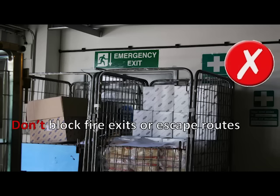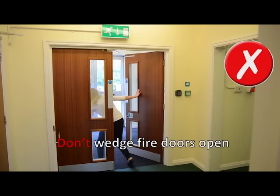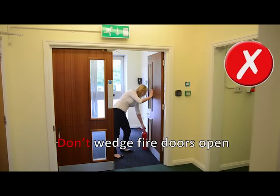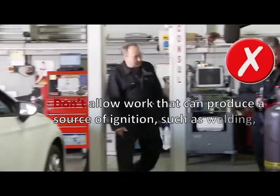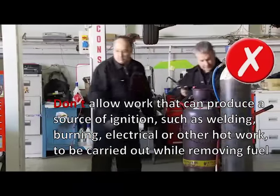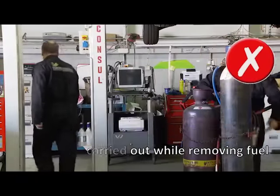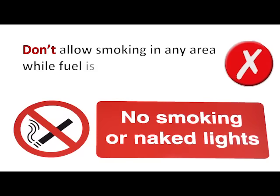Don't block fire exits or escape routes. Don't wedge fire doors open. Don't drain fuel over or close to a pit or a drain. Don't allow work that can produce a source of ignition, such as welding, burning, electrical or other hot work, to be carried out while removing fuel. Don't allow smoking in any area while fuel is being removed.